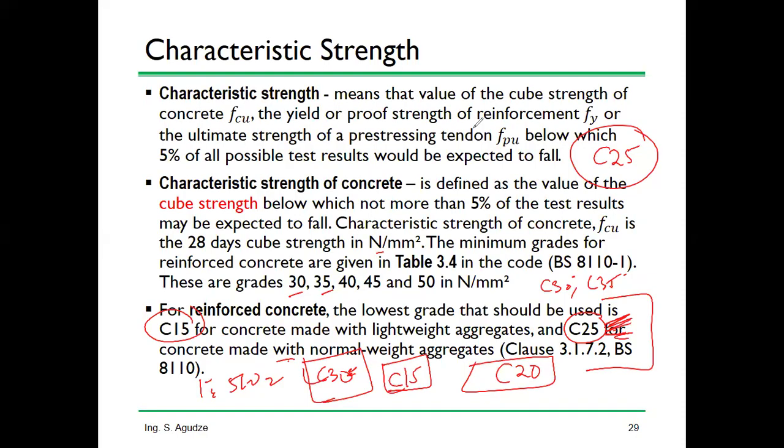So there's nothing like half bag. That's what I'm warning you people about. That half bag and whatever is baseless. If it is 1:2:4, you must measure it as such. If you are using half bag, and the ratio is 1:4, whatever, it must still remain in the ratio.